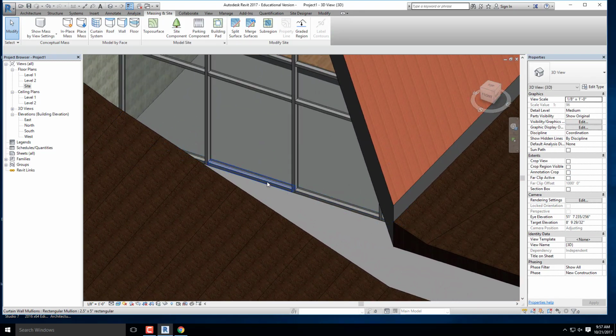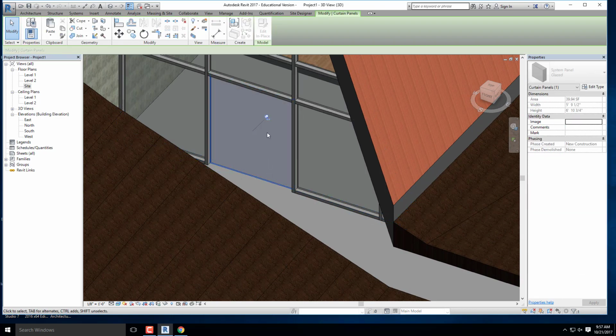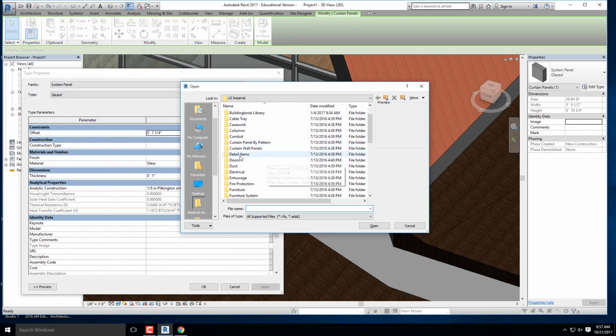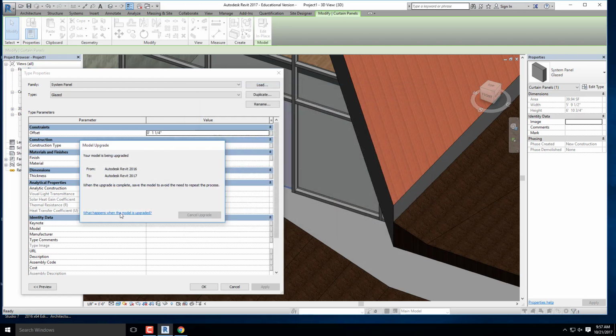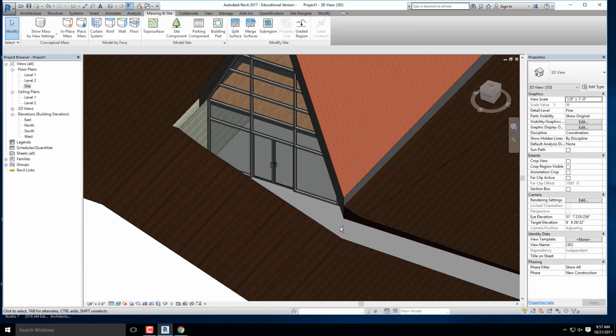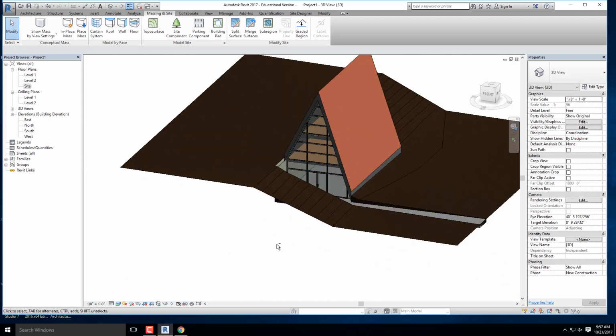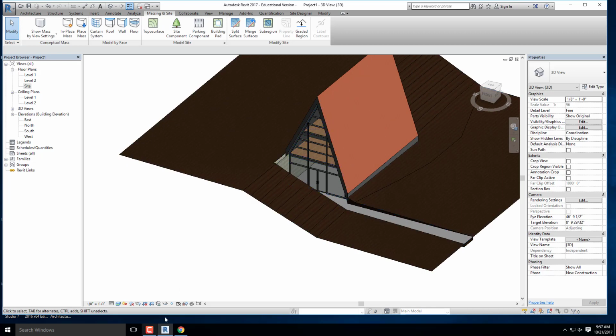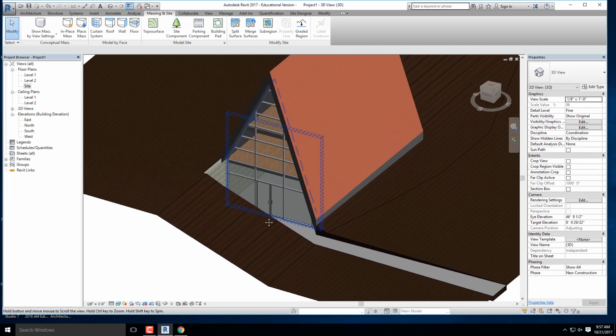Right now we have this on 6-foot spacing, so I'm going to go ahead and remove that mullion. I'll select this space right here, and load in my storefront door. So I'm going to go to Doors, and go to Door, Curtain Wall, Storefront. Hit OK. And there we go. We have that door. I can change the detailing to fine if you want to see the door handles. And you can see that this little cabin is starting to come to life. That's pretty close to the more finished product that I showed you earlier.